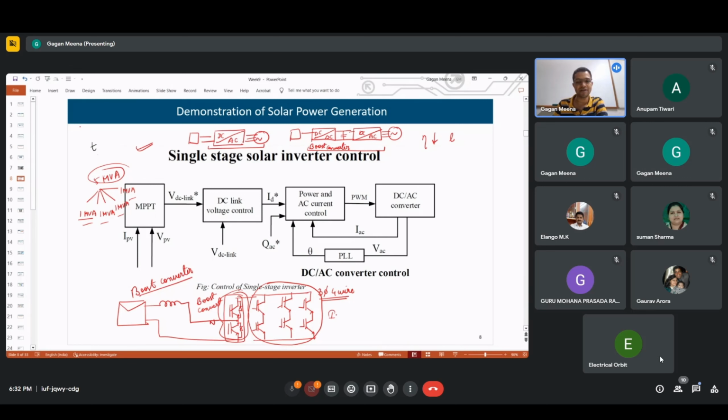Because an actual wind turbine has to operate at several different wind speeds, DFIG allows that. We can operate in sub-synchronous speed, at synchronous speed, or above synchronous speed.